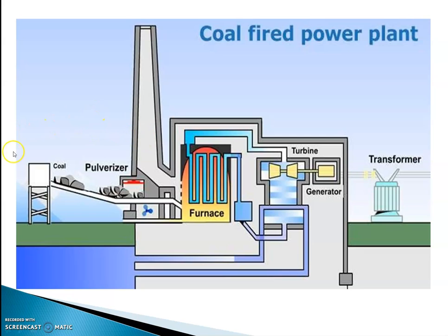The schematic view of the thermal power plant shows how electricity is produced with coal as a fuel. The coal, as pulverized fine particles, enters the combustion chamber. The flue gas then enters the furnace around the boiler tubes, where water is circulated, and steam is produced. High pressure, high quality dry or superheated steam is formed.